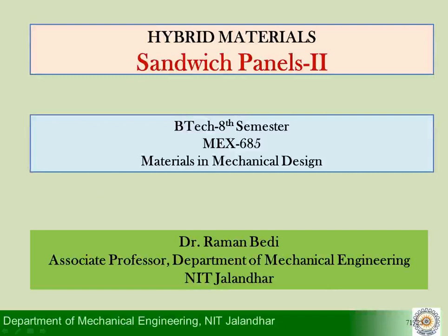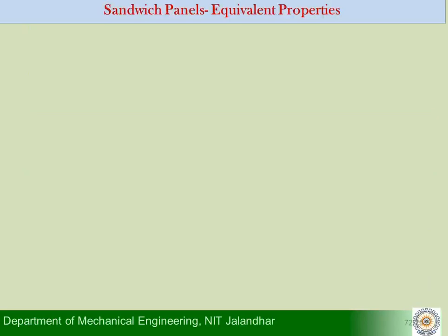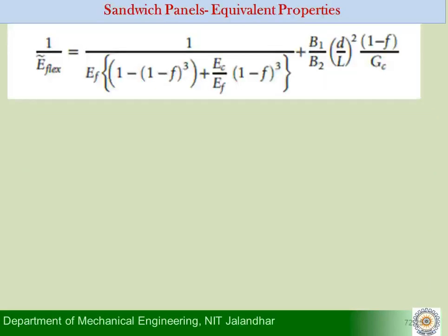Yes, coming back to our discussion on sandwich panels. What we have seen lastly is that we were able to get an expression for the equivalent flexural modulus for the resulting sandwich structure, which is this equation, written in terms of the volume fraction of the face material, that is F, the modulus of the face material EF, the modulus of the core material EC,